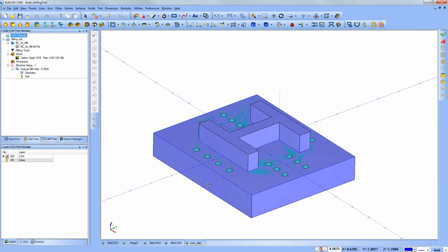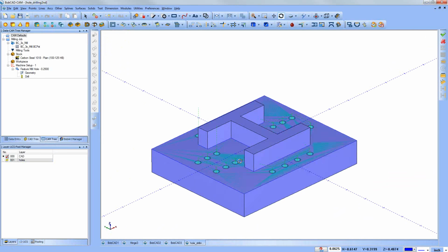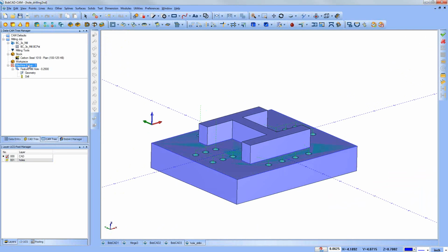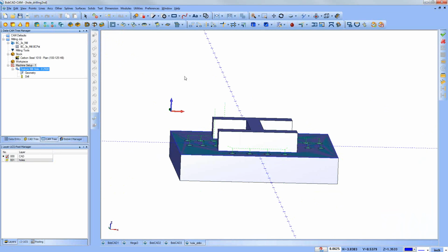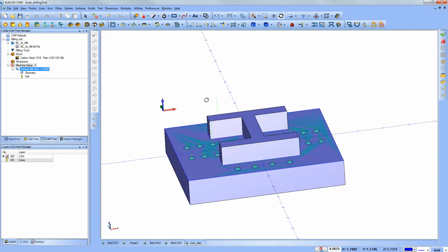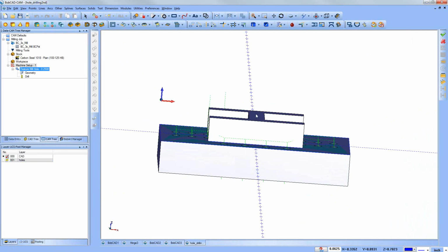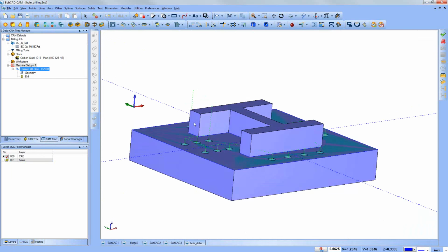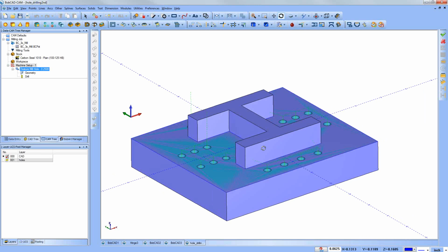So in this case, I've selected these holes. Okay, and my top of part happens to be here. Let's say I'm touching off some datum here of a stack up or something like that. Top of part is here in line with the top of this boss. My holes don't start till the bottom of this shoulder, this level of this geometry.